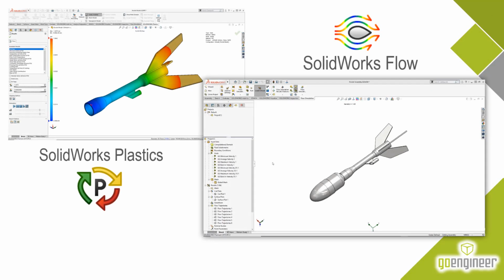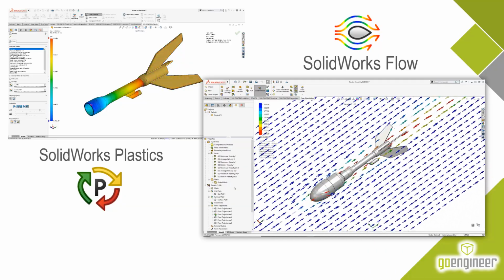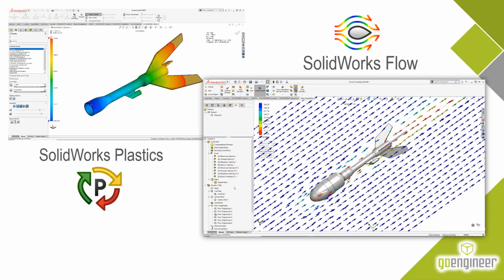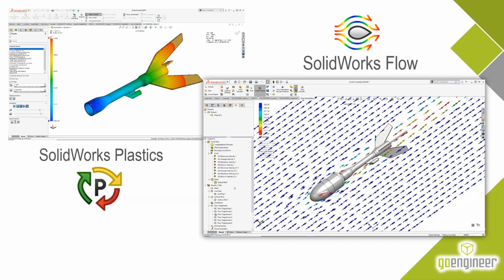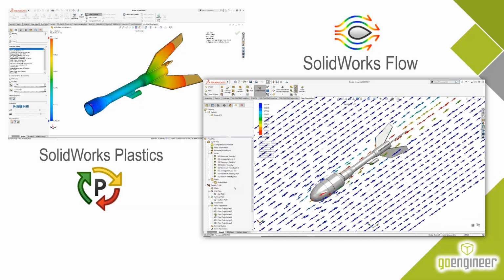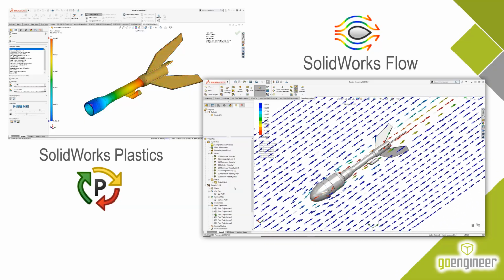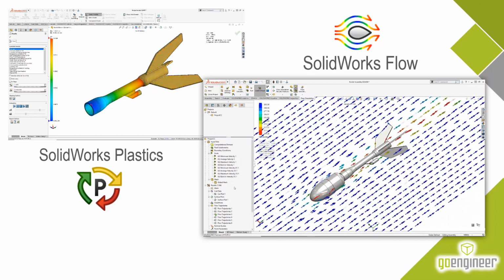So what's next? Well, if I was going to go to physical production on this particular part, what I might want to do is jump into SolidWorks a little bit and leverage some of the other things that we do very commonly. Whether that's SolidWorks Plastics, where you're going to actually see where the best gate points are going to be, maybe have a complete runner system and a multi-cavity tool, find out how long it takes to hold the part and pack it, and then let it de-stress so the residual stresses in the mold can release. When you open it, your part can come out perfectly stable size-wise.